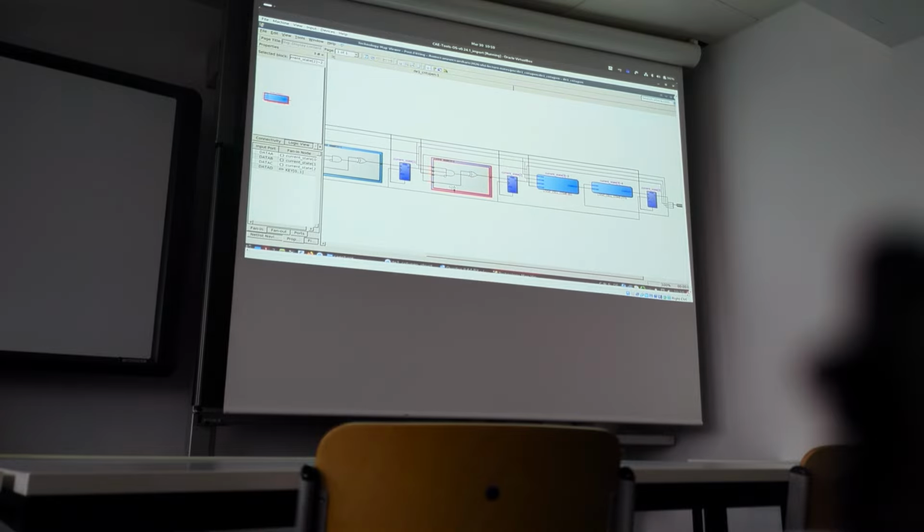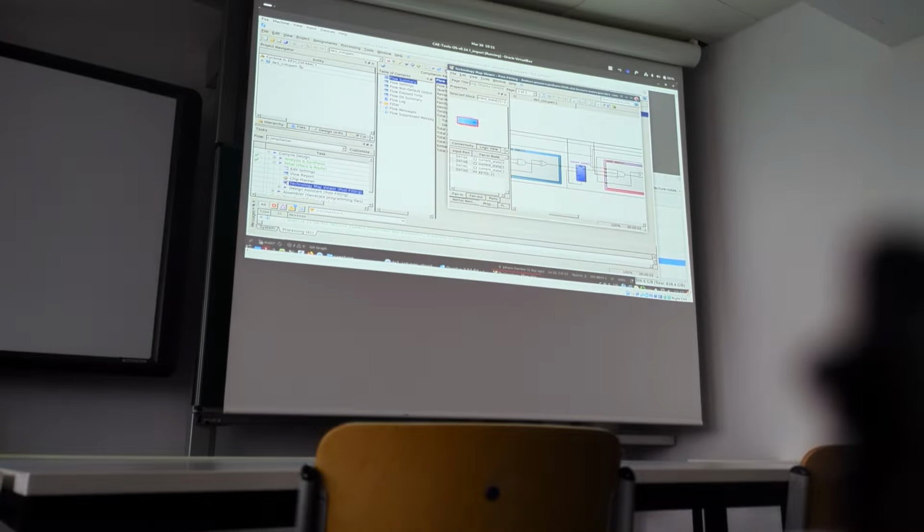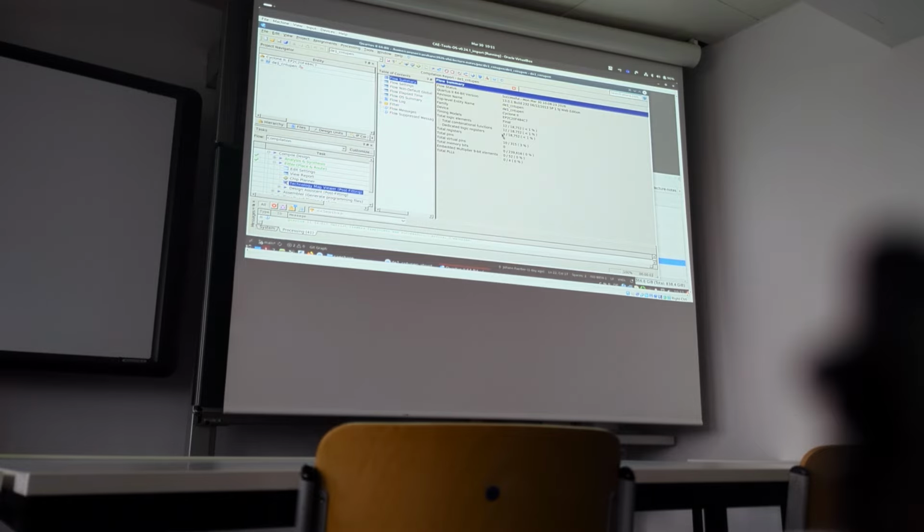So some lookup tables are necessary, a special amount of lookup tables. How can we find a summary of that? If we close that and look at the total logic elements, it tells us we need 12 logic elements here. And from the 12 logic elements, we need 4 registers, something we expect actually.